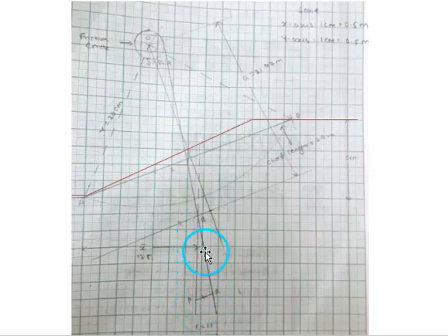Then we have to draw a line parallel to this total cohesive force like this, so that this triangle is formed. From this force triangle, we can measure the distance, this PR, which represents the total cohesive force. Suppose it is some 1 centimeter, multiply with the load scale. So that we will be getting the total cohesive force.